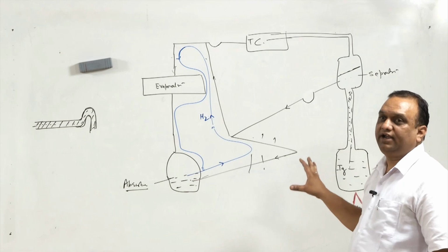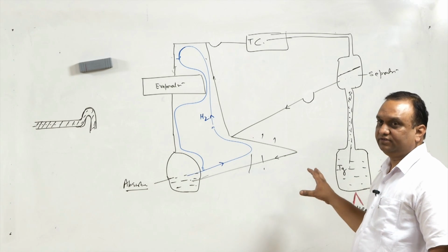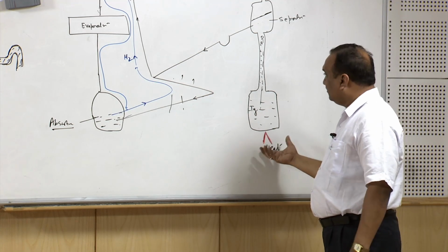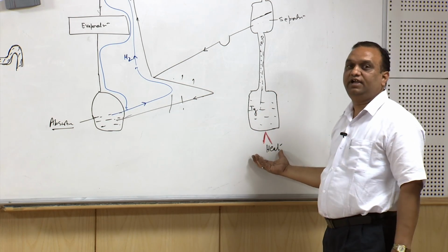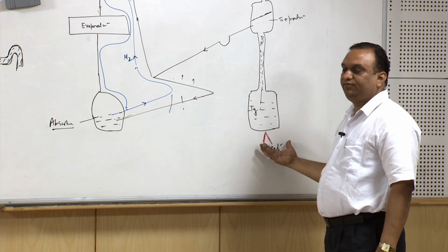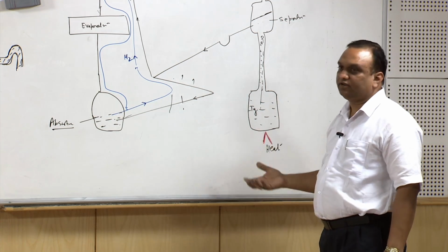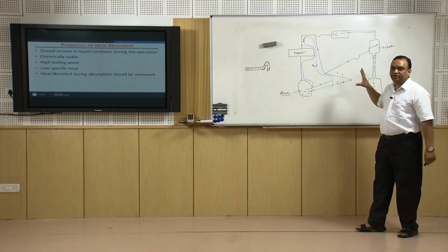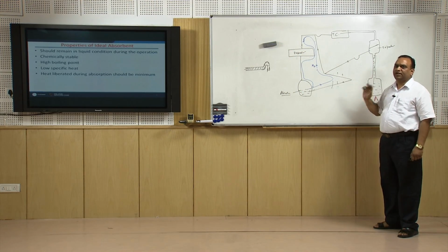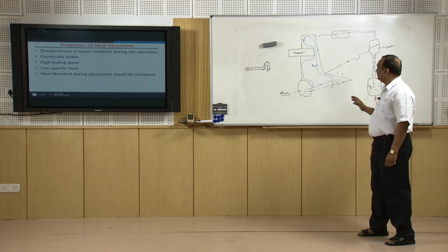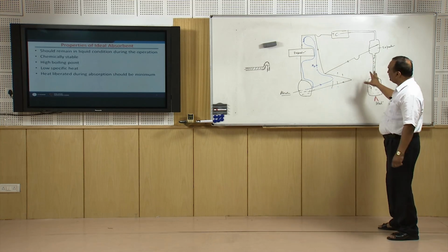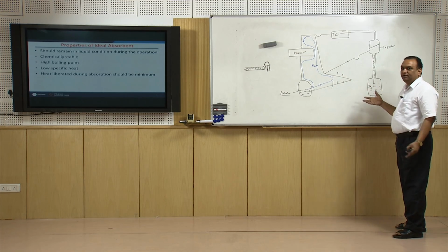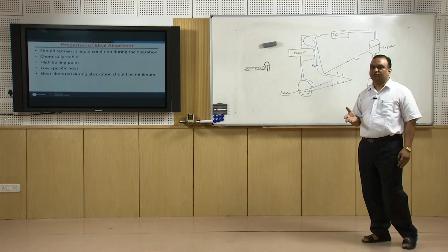If there is no moving part, it means external energy is not required in the system. Once external energy is not required, it means simply if I provide heat, some heat is available here, or if you go for these types of refrigerators, because Electrolux is a company which used this concept and went for the mass production of Electrolux refrigerators working on the 3 fluid system. So, this system is very good for rural applications where there is no electricity.